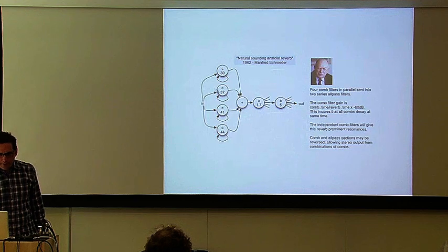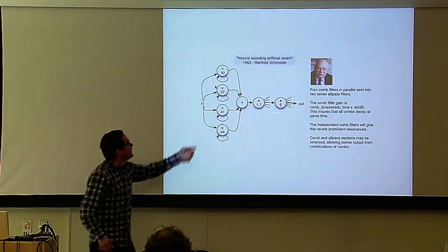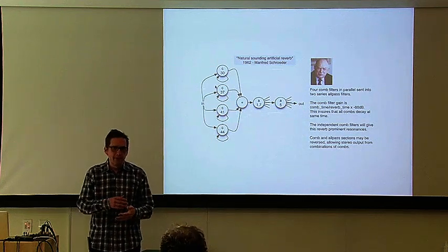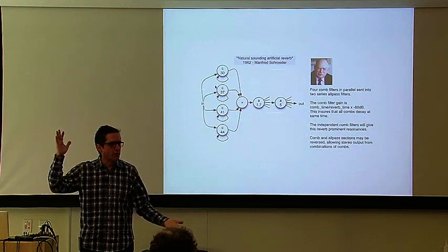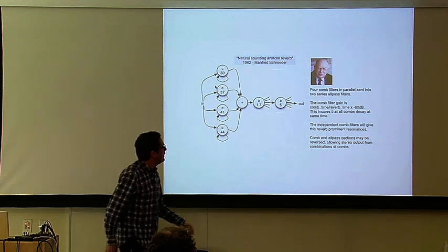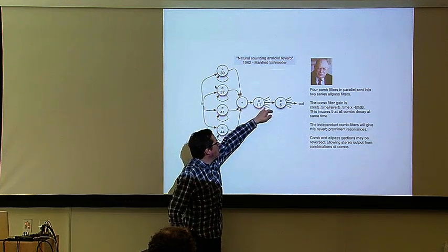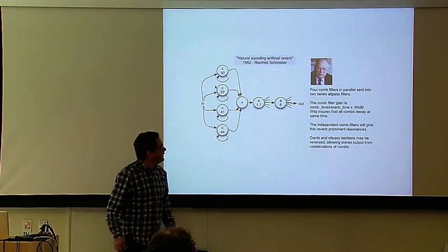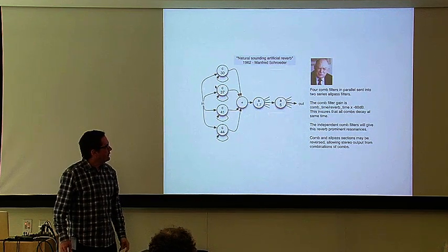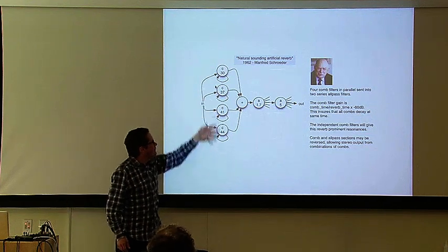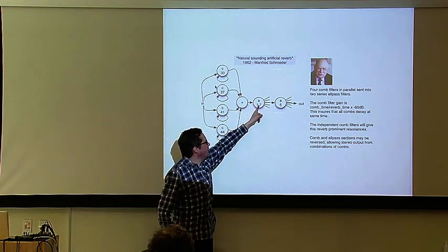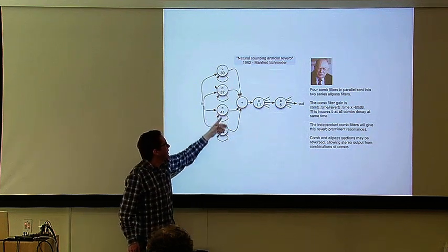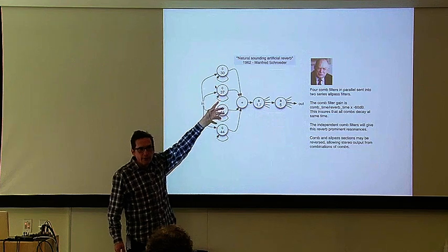The comb filters are tuned to things like 30 milliseconds, 44 milliseconds, more or less the reflections in a room, the size of a room. The all-pass filters, though, are set for very short times, and what they add to this network is that they fill in a little complexity in between the primary echoes in the comb filters.